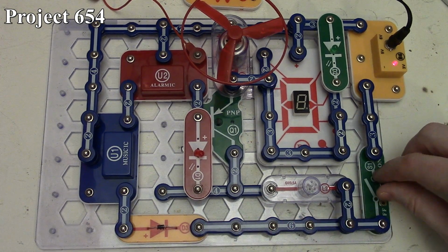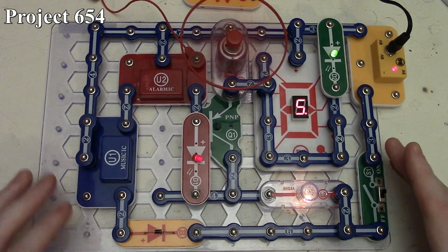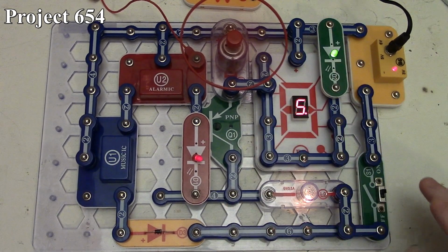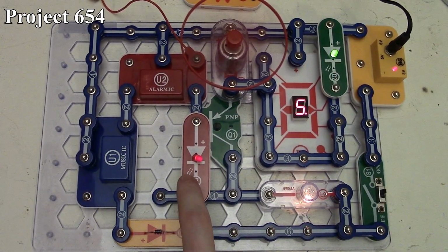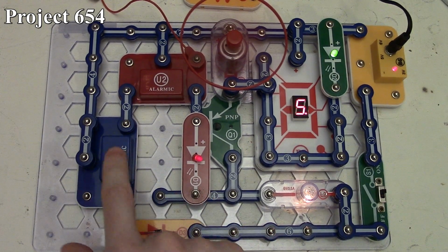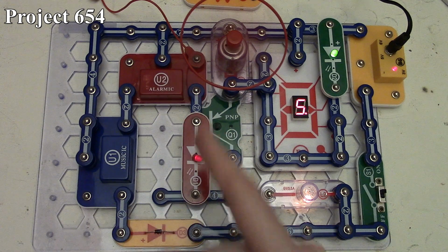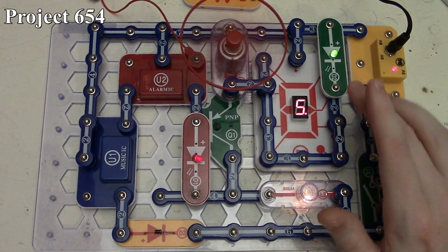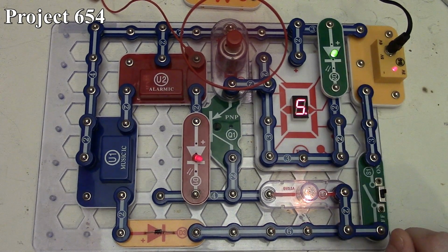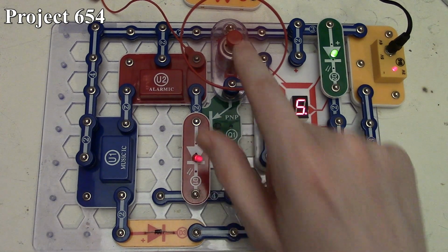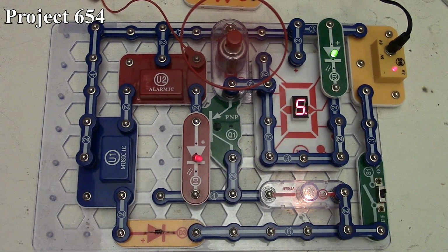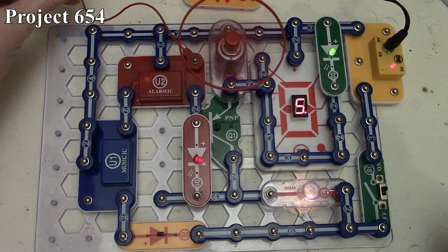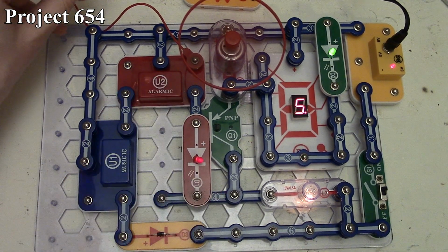So when we turn on the circuit this time, our motor speeds up quite a bit and our red LED is nice and dim, and you see that it momentarily pulsed there when the music IC stopped and then was restarted again. We still have the letter S or number 5 showing, depending on your interpretation, and our green LED is lit up nice and bright, which is helping to feed it, along with our 6-volt lamp, which is in series with our motor there.